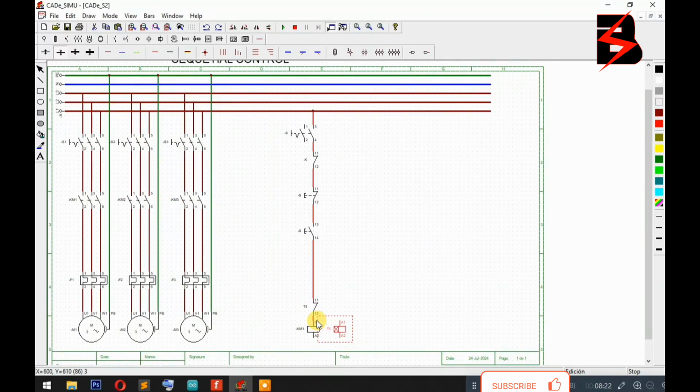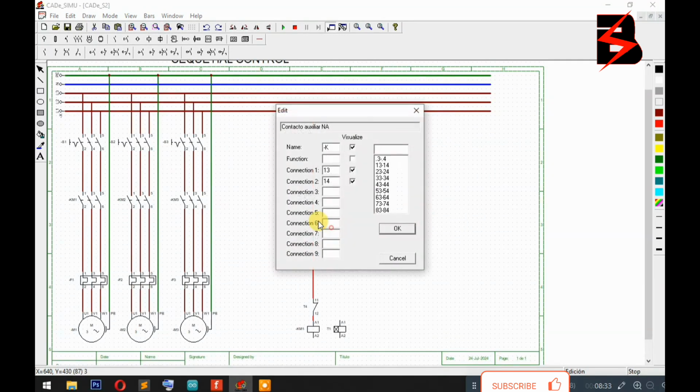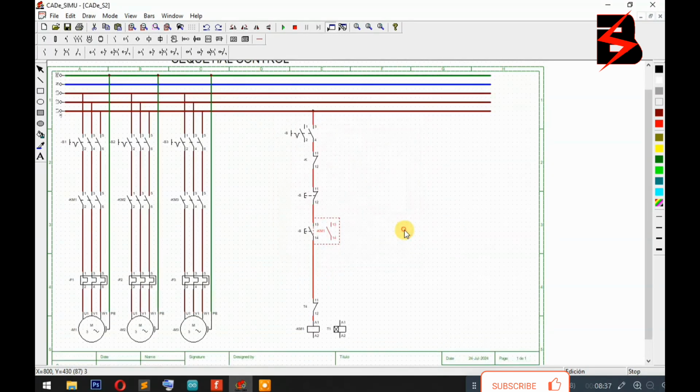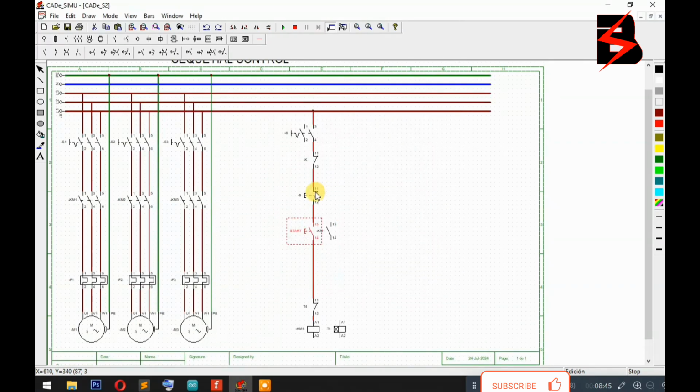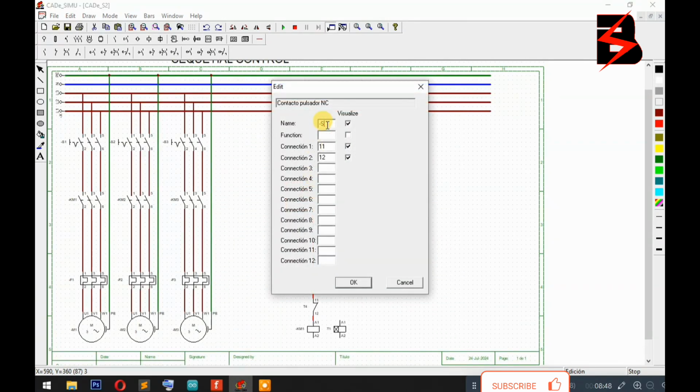I think. Then contactor 1 is going to self hold itself. How? Through a normally open contact here, around there. So this one is a contact of KM1. There we go. This switch, I'm going to name it start. As I told you, this one is just emergency, not a stop. It is the emergency.